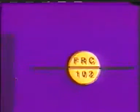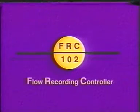Here is the symbol for another controller. The letter F stands for flow. Flow is the variable being controlled. The middle letter R stands for recording, and the end letter C stands for controller. So these letters tell us that the instrument is a flow recording controller. The loop number appears in the bottom of the symbol.